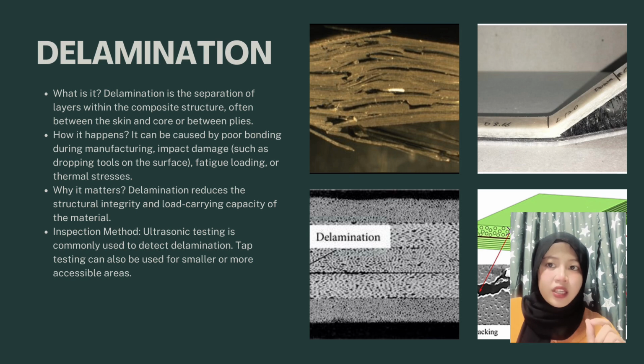Fiber delamination is the loss of bonding. It happens between the plies, the layers in a laminate composite. But now we are going to explain about the fiber delamination in sandwich structure. The fiber delamination in sandwich structure often occurs in 2 situations: between the fiber layers and the fiber layers, and the second situation is between the fiber layers and the core layers. But it will not happen within the fibers themselves.